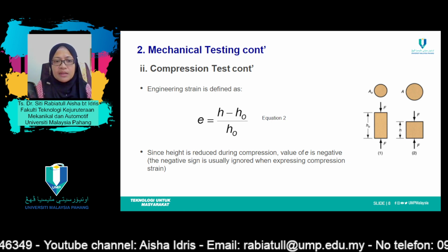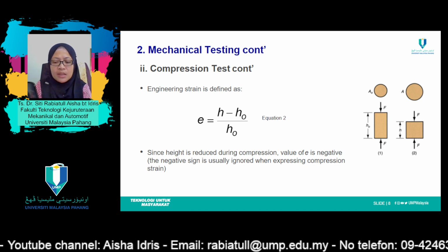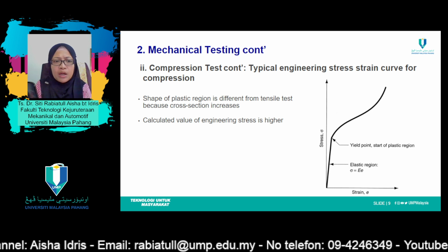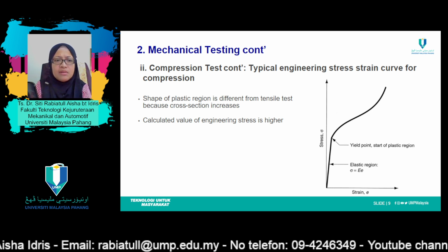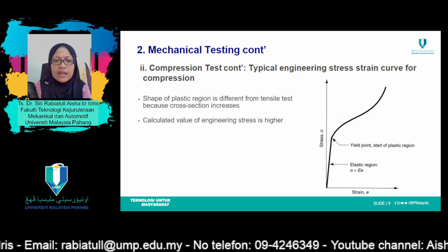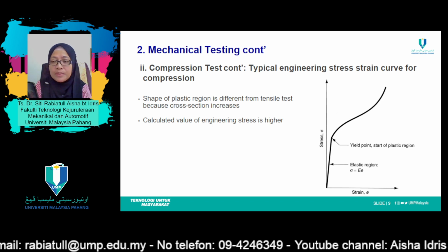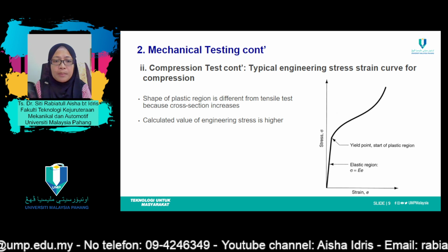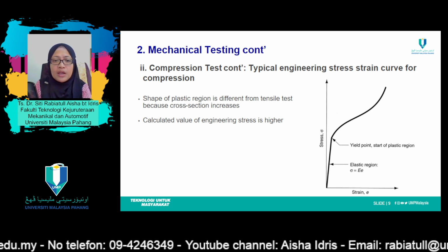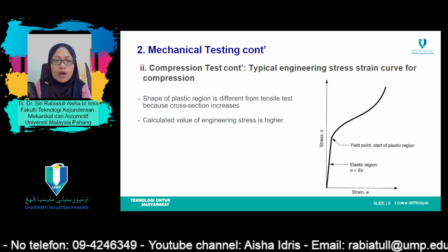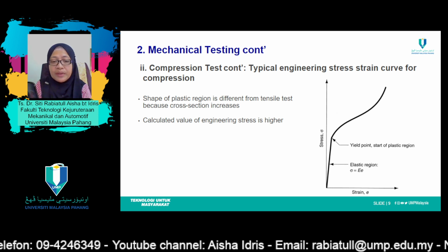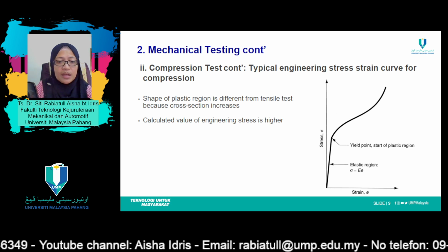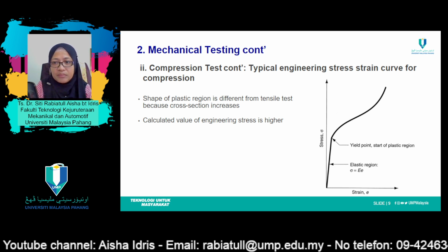Tensile tests are more common because they are easier to perform, and also for most materials in structural applications, very little additional information is obtained from compressive tests. Therefore, compressive tests are used when the material's behavior under large and permanent strain is desired, as in manufacturing applications, or when the material is brittle in tension.